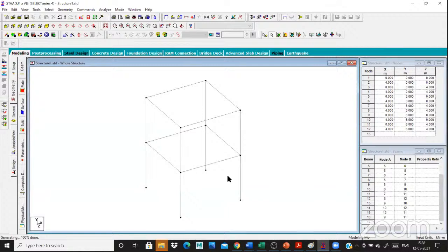There is a ductility detailing code book. You provide the additional reinforcement for earthquake. That is a method to design the additional reinforcement, the detailing method. Also there are many dampers, viscous dampers, and other types to resist.